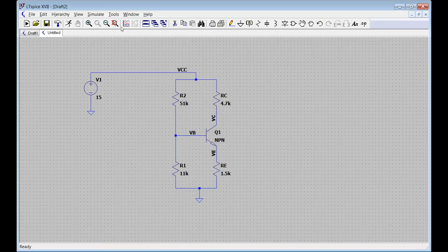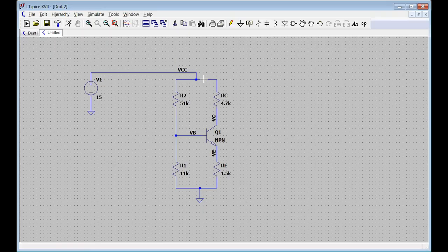I want to try to do something. It may not be in this version where I can highlight all the nets. Let's see if it's here. Yeah, here we go. So if I want to know what's all connected to these transistors, I right click on this node here. Oh, excuse me, the other right click, and hit highlight net, and it shows all of the nets that's VCC.